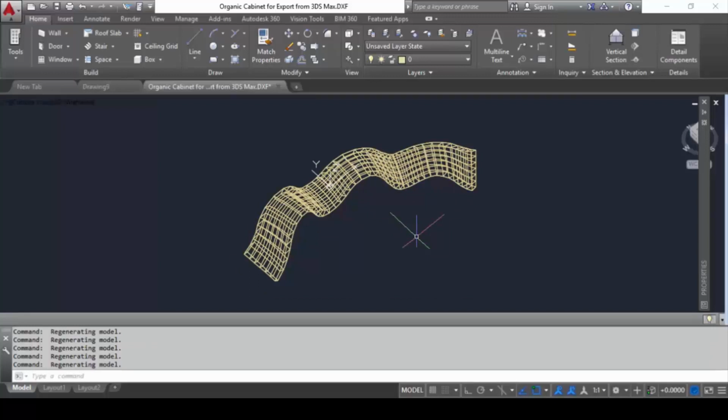Look, again, life is very, very easy when you have only this one little curvy line to export. Life is beautiful, but in your case, it can be a 45,000 face 3D model, I don't know. So life would not be so nice nor easy to export. Many a times you need to export them in pieces, in parts, or in layers, and not one shot, because there is a limit to how many faces one export command can do at one time. Usually about 32,000 faces, so be quite careful with this.